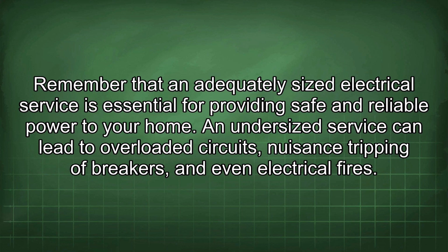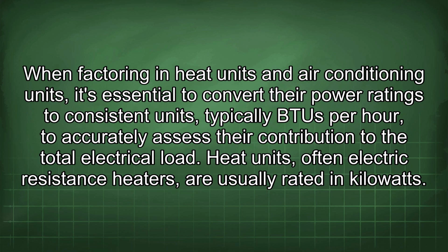An undersized service can lead to overloaded circuits, nuisance tripping of breakers, and even electrical fires. When factoring in heat units and air conditioning units, it's essential to convert their power ratings to consistent units, typically BTU per hour, to accurately assess their contribution to the total electrical load.